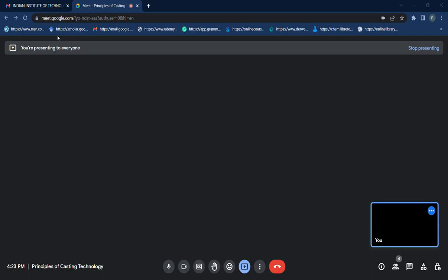So from here, you can see the volume of the riser. If I go to 0.5, you can see that the volume of the riser is around 30% of your appendage.